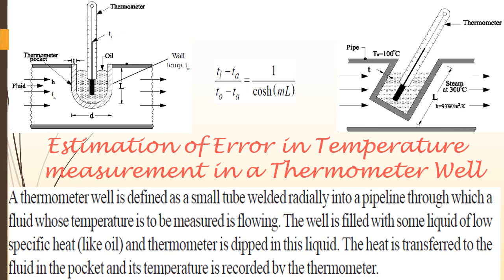In that case, to measure the temperature of a flowing fluid, like a fluid flowing through this pipeline, if you want to know the temperature of this fluid, these kinds of thermometer wells are provided, in which we put the thermometer, and this thermometer will give a reading that informs us of the temperature of the fluid flowing through this pipe. So this is a very old technique.